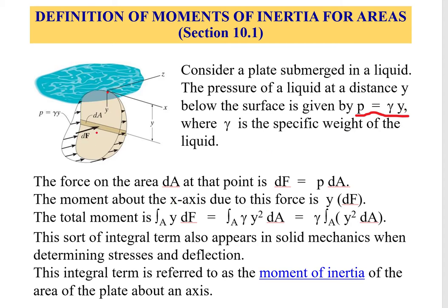Now, to calculate the force applied by that pressure on a strip, we know the relationship between force and pressure is that force equals pressure multiplied by area. Since we are talking about a fragment, or differential, a small force dF is equal to the pressure multiplied by the small area dA. Therefore, the force is related to the pressure in a small fragment by dF equals P dA.